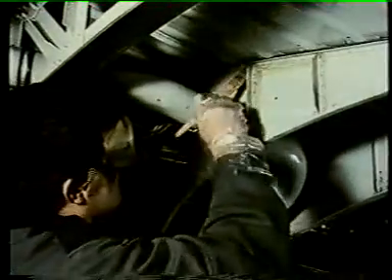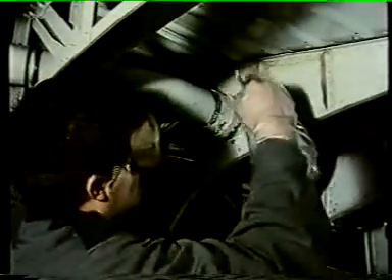Additional medium-term protection can be obtained by using PX32. This is a solvent-based wax protective, and it can be applied either by brush or by high-pressure spray. It dries within 24 hours to give a tack-free dry coating. Since it's transparent, surface deterioration or cracks can still be seen.